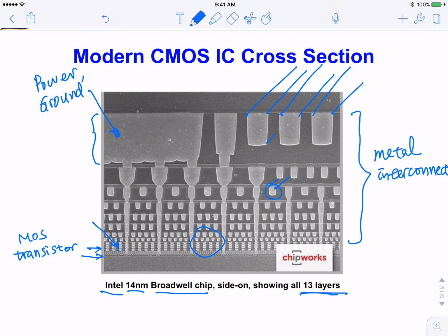It looks very regular here, so it almost looks too regular to be a wire. So sometimes in order to ensure the uniformity of the process, they put dummy squares there. Even though you don't have any metal interconnect there, they put metals there for nothing, so that when they do the etching, they always see a similar fraction of metal areas.